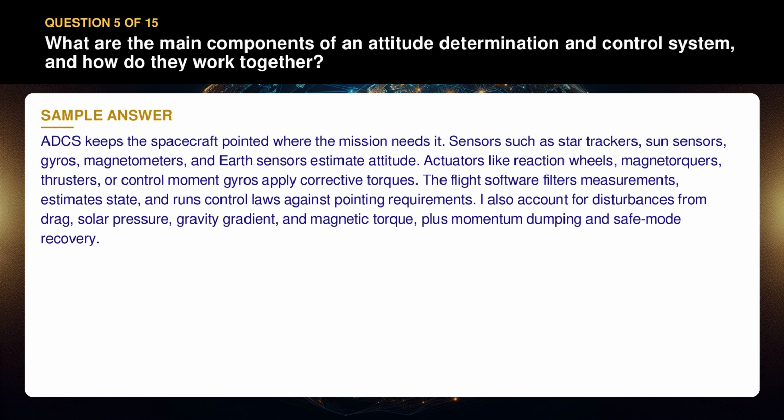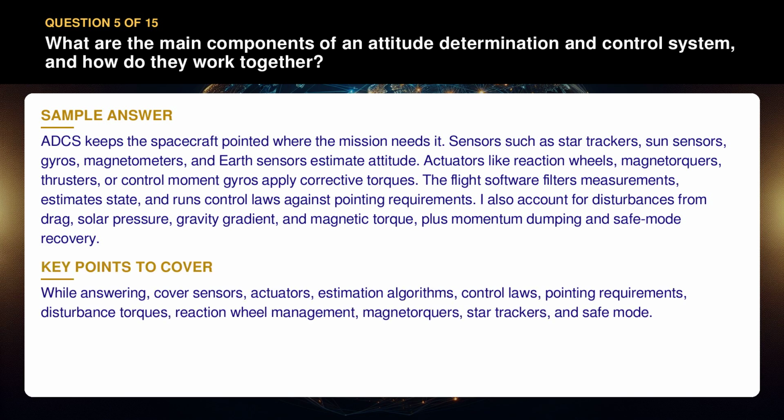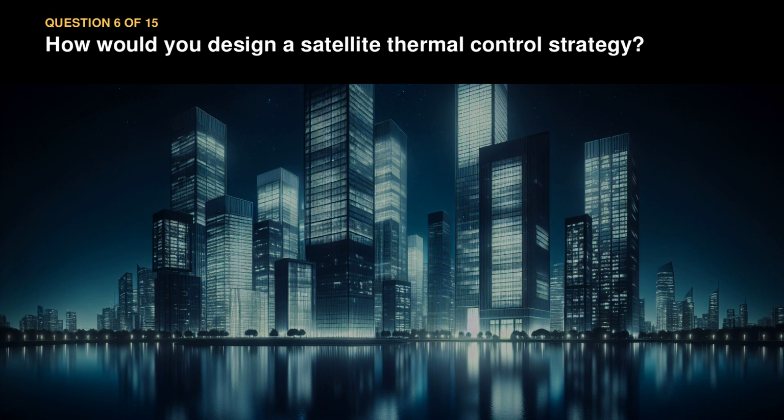I also account for disturbances from drag, solar pressure, gravity gradient, and magnetic torque, plus momentum dumping and safe mode recovery. While answering, cover sensors, actuators, estimation algorithms, control laws, pointing requirements, disturbance torques, reaction wheel management, magnetorquers, star trackers, and safe mode.